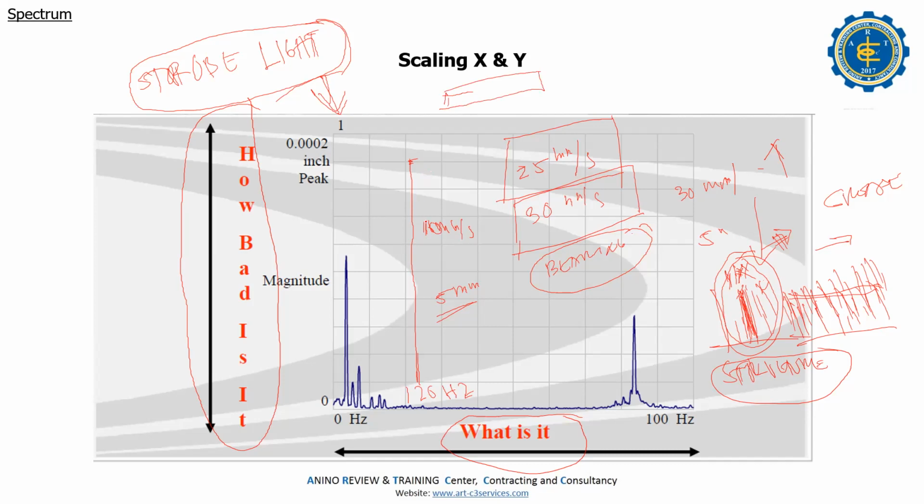When I used this, I thought the equipment was shut down. I told my superintendent, the equipment shut down. But it's running. I took away the strobe light, then I saw the shaft running. I focused the light on the shaft, and it stopped.